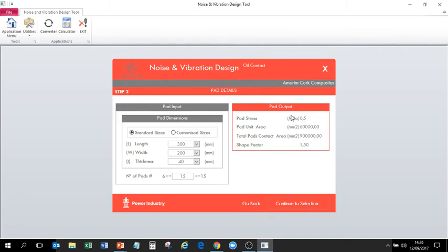the pad stress decreased to 0.5 megapascal, which is basically, instead of knowing that material should work between 0.5 and 1.5 megapascal, with the stress limits of the material, the user doesn't need to know that information, because the software will define the limits not based on pressure, not based on deflection, but based on number of pads, which is much easier. And again, if we have 7 legs, we could use 7 pads or 14 pads. Let's try the 14 pads.